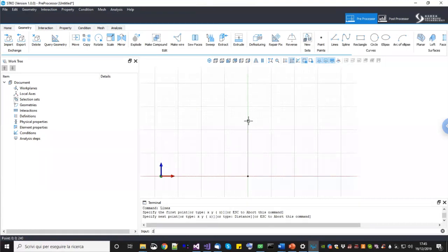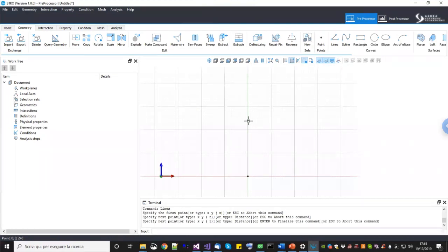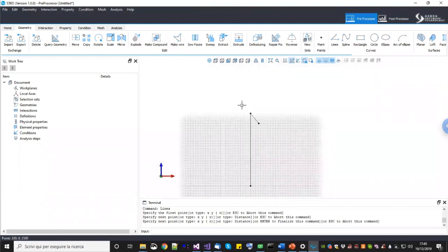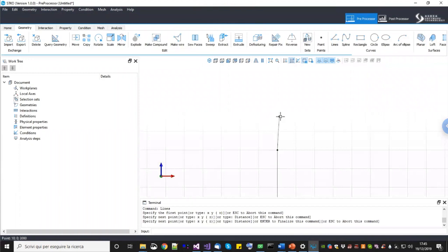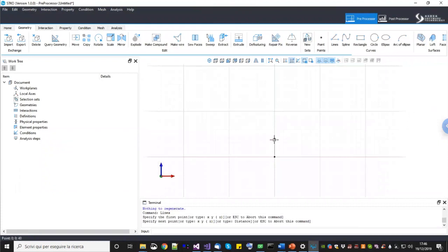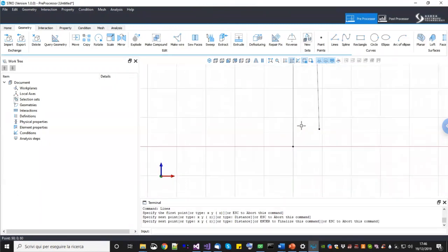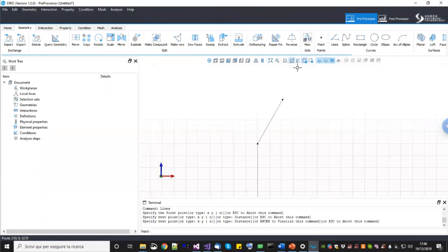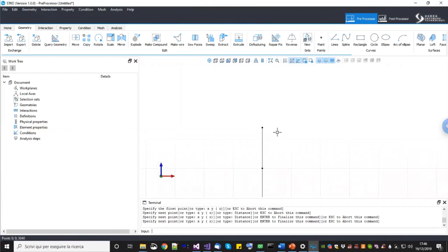So I'm going to create a column of 2.9 meters, and then I will create an extra 10 centimeters, here, or let me go back because I made it. How do you know that it is 2.9 and 10? Well, I was trying to replicate an example, but 2.9 because I'm writing here in the input file, like 2.9 meters, okay? And then an extra 100 millimeters. If you want to draw only on the orthogonal direction, you go like this, so 100 millimeters, and I'm fine.